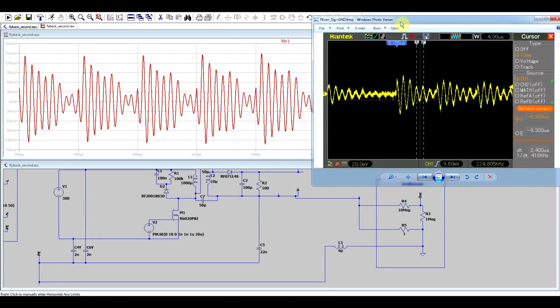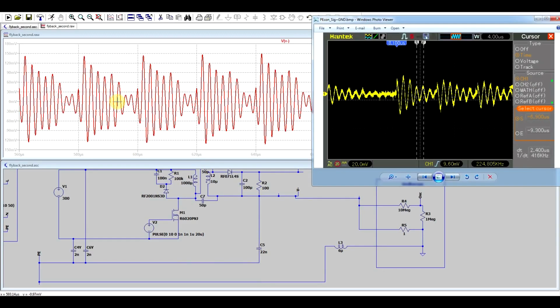And this time the waveform does look like the measured thing. So what we're seeing here is energy coming from the switching supply, coupled through the transformer, through the stray capacitance, and then causing a ringing through the protected earth supply network because of its inductance. The voltages are not exactly the same, but the phenomenon is being reproduced correctly.